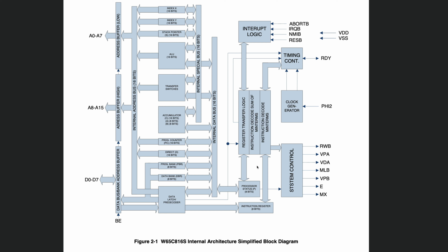And indeed, the behavior of the CPU when you bring bus enable low is not defined. It will just crash. So in order to implement DMA and use the bus enable pin, we have to stop the CPU from executing. And this will also help us resolve the situation with our latch, because if the CPU is stopped, then it doesn't actually matter what the latch is latching at that moment.